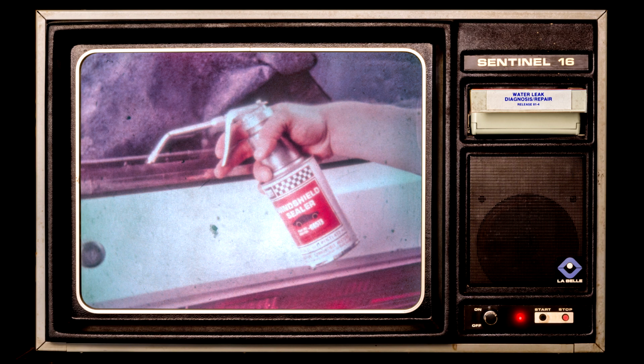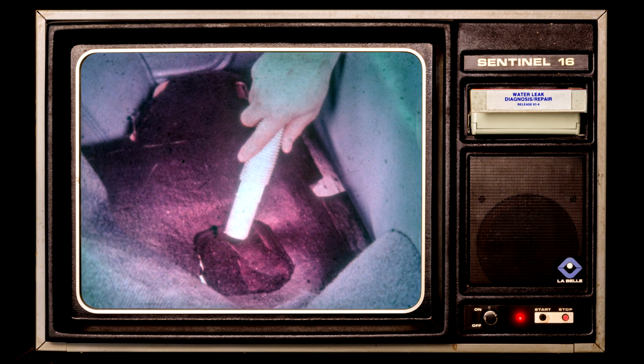This procedure is also applicable to leaks between the channel and body. Always be sure to clean up any excess sealant following the instructions printed on the container. Then retest the leak area to be sure the leak has been sealed. And finally, vacuum the water up and, if necessary, shampoo the carpet in the leak area. Be sure to inform the customer that the damp carpet will require a couple days drying time.